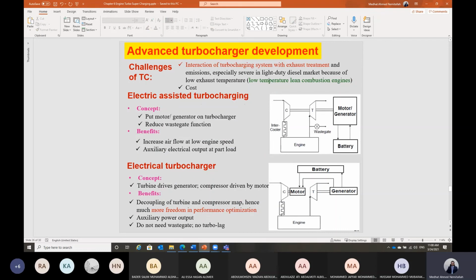Okay, here, Shabab, are some modern designs of the turbocharger. We have a challenge with the turbocharger, as I told you, that it increases the temperature of the combustion and the pressure inside the combustion chamber. And this applies if we have higher temperature. First of all, there is a possibility of knocking in the case of a gasoline engine. And second, we may have emissions, like NOx emission. The thermal NOx results from high temperature combustion. So in this case, Shabab, this will interfere with the operation of the turbocharger, because having a turbocharger will result in higher engine emissions.